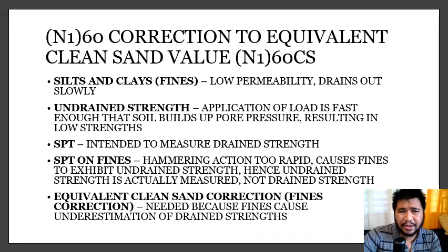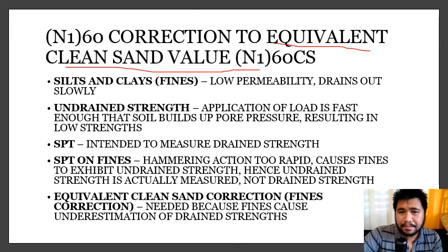Now, correction of SPT into the equivalent clean sand value, or the N160CS. CS means clean sand. So why do we do this? First, you have to remember that silts and clays, or what we call the fines, have low permeability and drain out water very slowly.